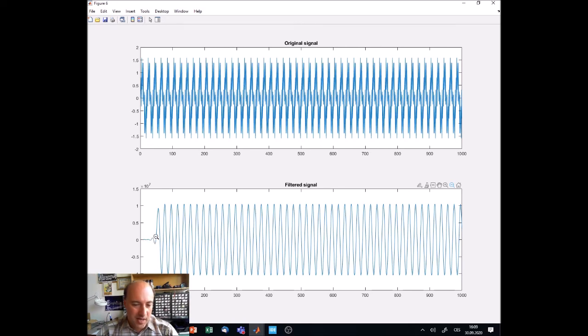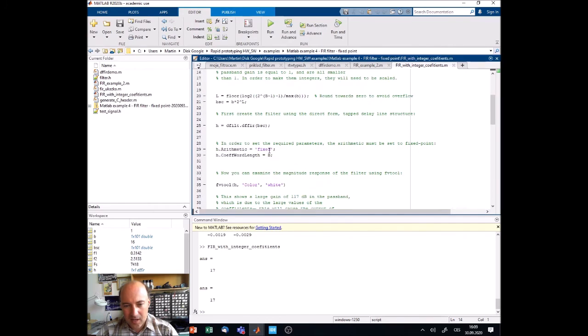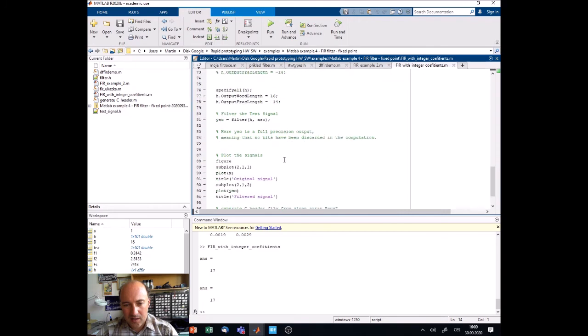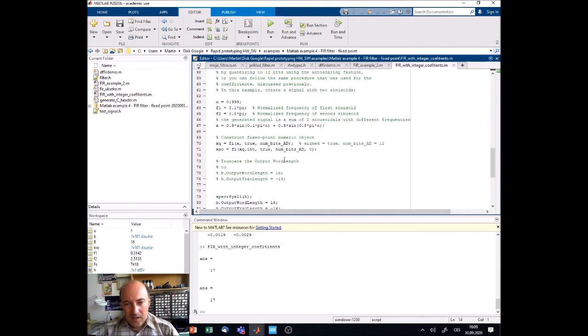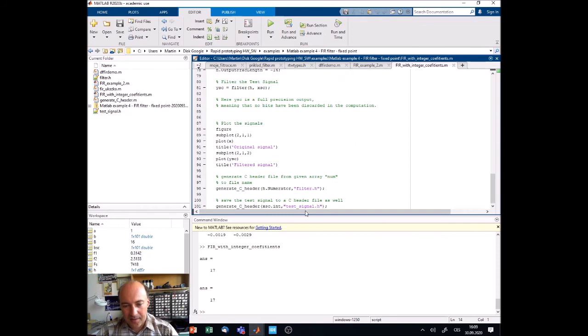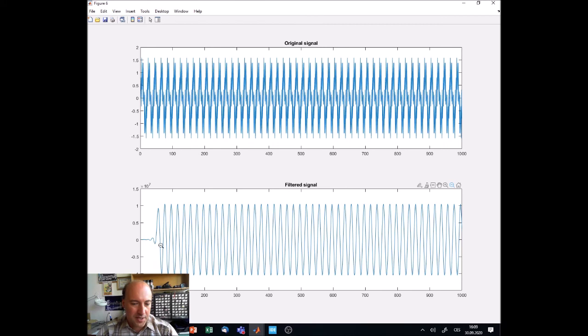And since in my example the length of the filter is relatively large, I have designed the filter length to be, I don't know, something like maybe 50 to 100 samples, so maybe 80 samples long.